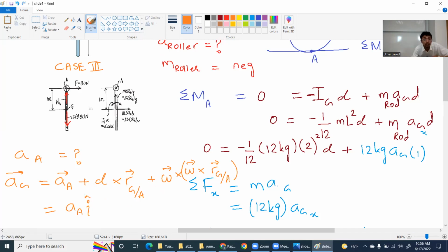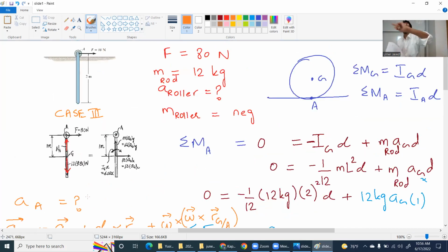Now be careful. Be very careful. The roller is also only going in a flat horizontal path, right? In instances when you have an object that is rotating, then we can easily fall into the trap, right? We have to be careful that an object that is rotating will have two components, right? Tangential and normal. Here life is easy. Oh, come on. We will only have one component.